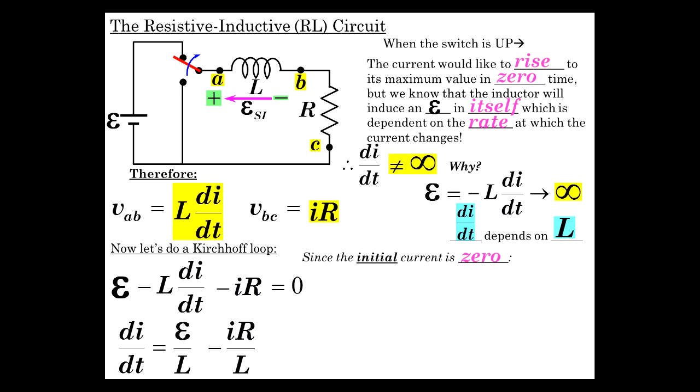Same thing as saying in mechanics, we start with an object of mass m from rest, and we apply a force. What's the initial velocity? Well, you know it's 0. Because the only way for it not to be 0 is for the acceleration to be infinite, which means you need an infinite force, which would of course obliterate the object, because matter doesn't have the ability to withstand an infinite force. The best you could say is it would turn it into a plasma in the attempt. Anyway, the initial current is 0 because di/dt can't be infinity.